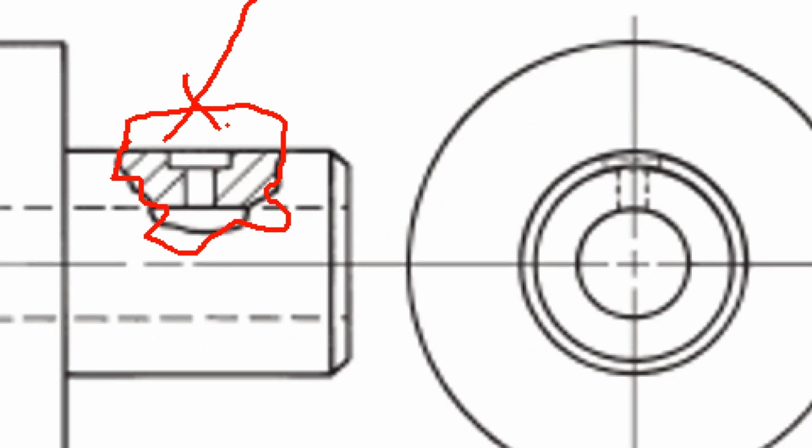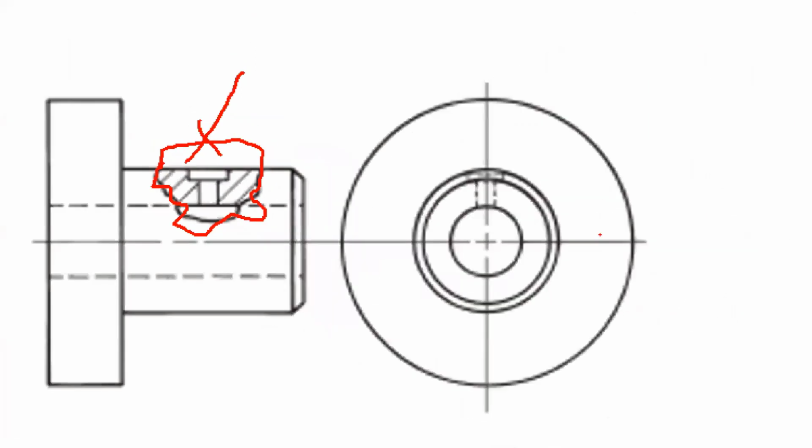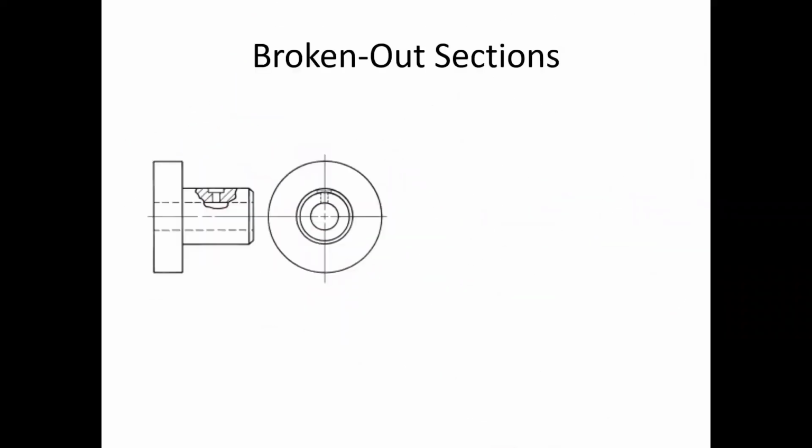If you're doing it in Inventor or SolidWorks, your sketch will have to be a fully closed loop. In Inventor, you would use a spline and make these zigzags so it's nice and curvy. Don't be afraid to click a lot to make this zigzag, really zigzag. What we're doing in this broken out view is just peeling back the material a certain depth until we can see what we want to see, in this case, that counter bore hole.